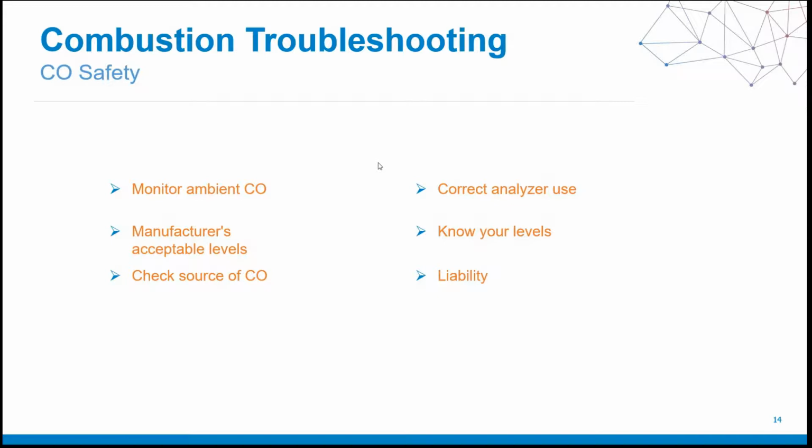You want to make sure that you're using your analyzer correctly. By that, I mean starting it up outside in fresh air and zeroing it out before you go inside and you test. And I'll touch upon that in a little while.